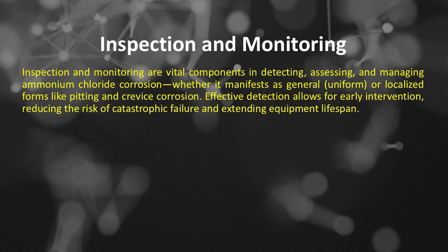Inspection and monitoring are critical for early detection, assessment, and management of ammonium bisulfide, NH4HS, corrosion in alkaline sour water environments. Different methods are employed depending on whether the corrosion is general, uniform, or localized, pitting, crevice. Below is a detailed explanation of the most effective inspection and monitoring techniques.